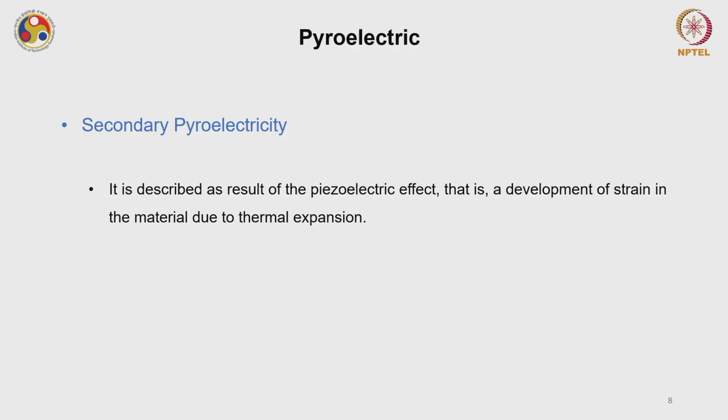Okay. At the same time, there is another phenomenon known as secondary pyroelectricity. This secondary pyroelectricity is described as a result of the piezoelectric effect, that is, a development of strain in the material due to thermal expansion. We will see how a thermal expansion, which is of course related to piezoelectricity, can in turn give you a pyroelectric behavior.